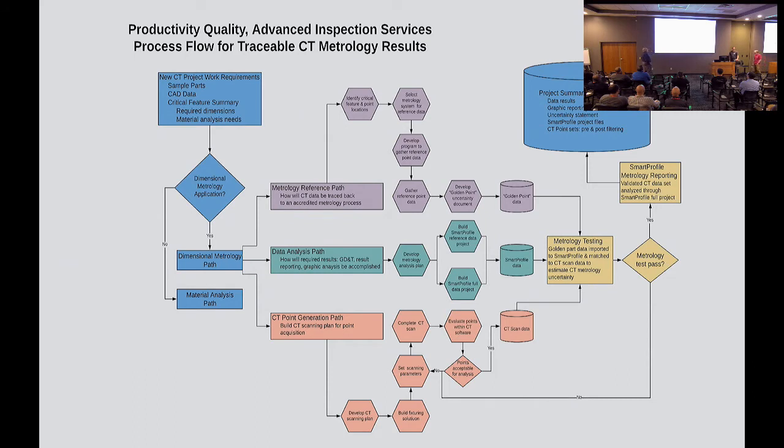Being measurement nerds, we're not going to go through the flow chart, but we sat down and talked a lot about it and said, how do we make sure? How do we know that these numbers are right? And that's something that we try to do a lot at AIS, is ask the question, how do you know? If somebody's running a CMM, is this going to pass? Is it a capable gauge for this application? Oh, yeah. How do you know? Oh, they say, well, okay, here's my calibration data, here's the artifacts they use. They can actually explain why people can have confidence in the results. So we came up with this big flow chart that we won't go all the way through, but it represents our thinking about how do you know.